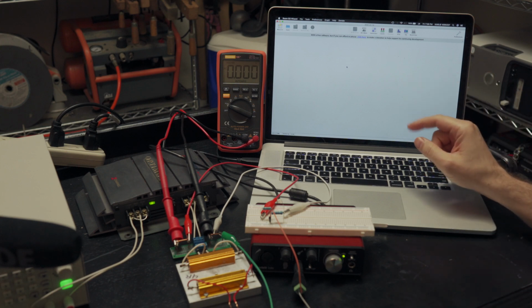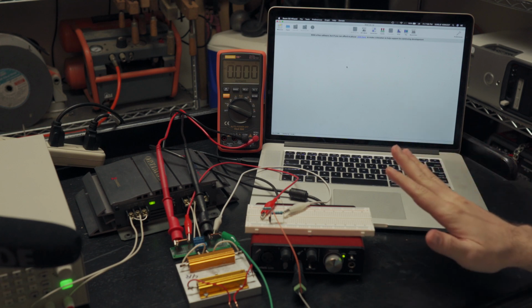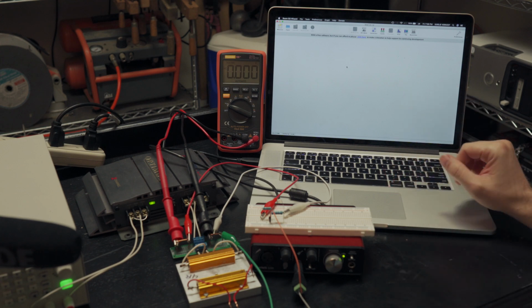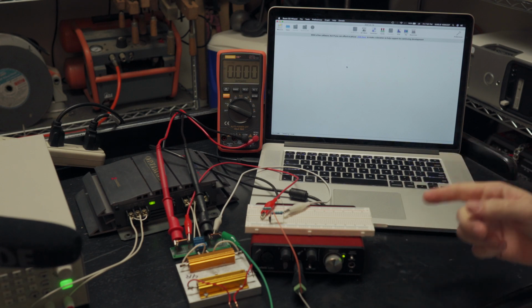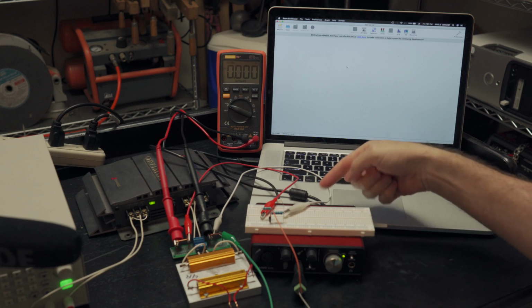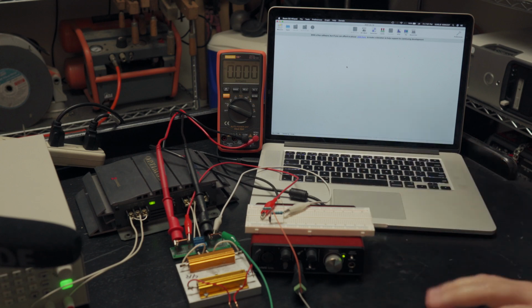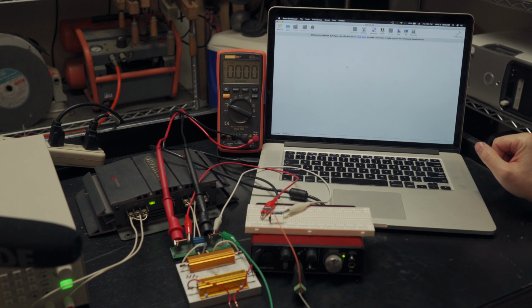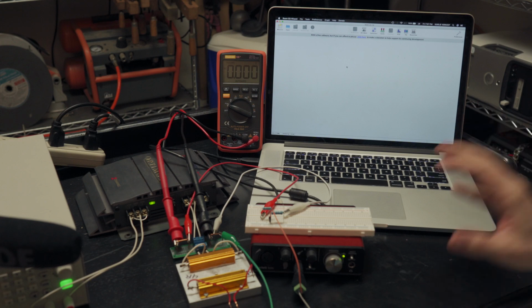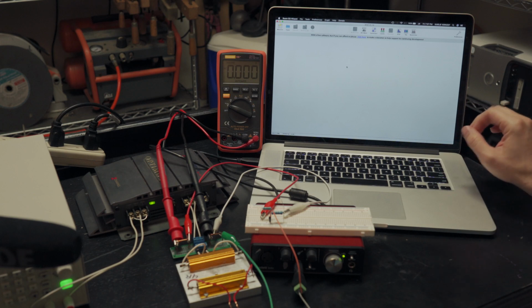So the first thing you want to do is measure your loopback to make sure that everything's cool. You just don't have any sort of distortion that you don't know about. Just make sure that the loopback looks good. In this case, I've already done that. Basically, with a loopback, you just run the output straight back into the input with a short cable and just measure the device itself. And this device measures 120 plus signal to noise and distortion of 0.00 something or other. And so it's more than up to the task of measuring this amplifier.